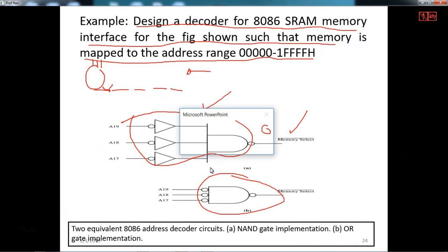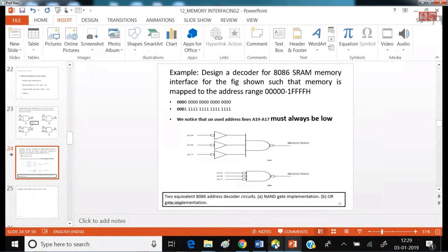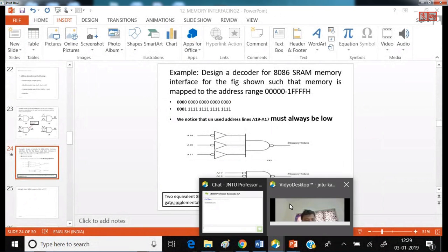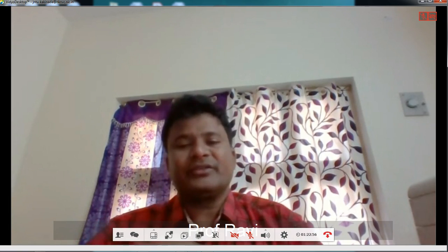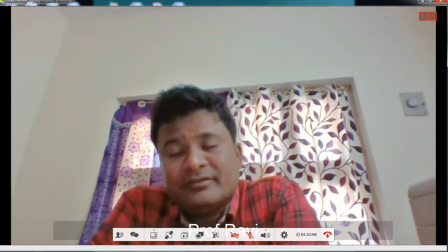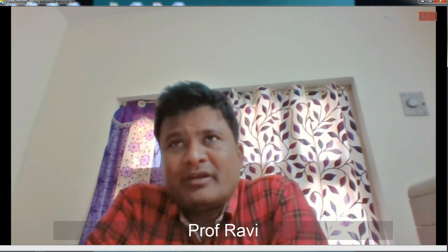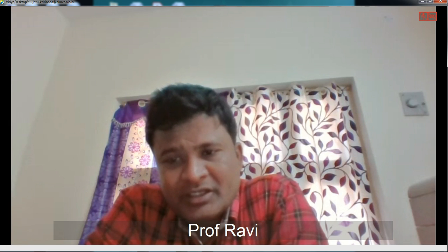So in this class, what I discussed in the beginning very clearly is what exactly the maximum mode of interfacing is. In the maximum mode of interfacing, we need to generate different control signals. Those control signals can be generated by using the 8288.